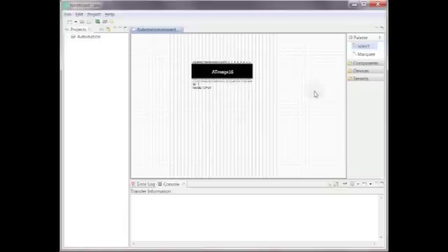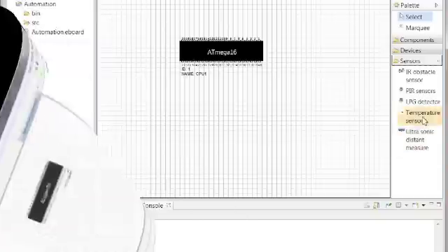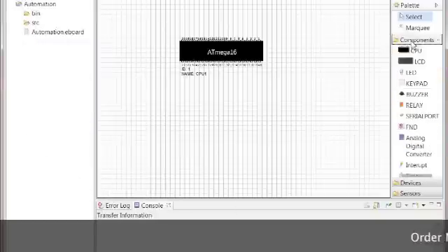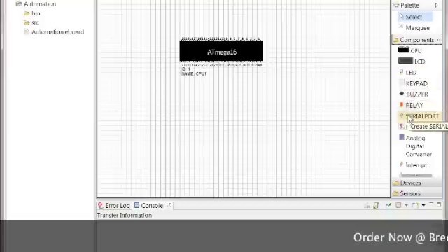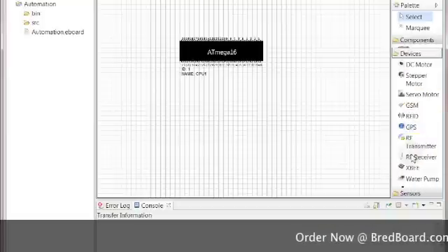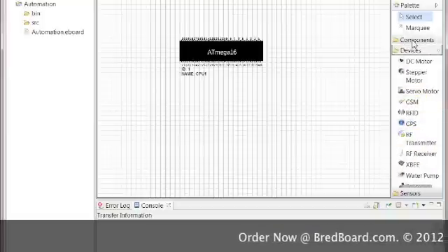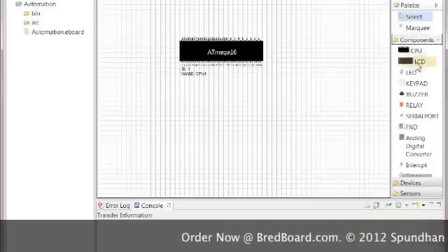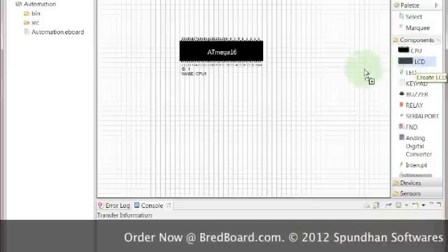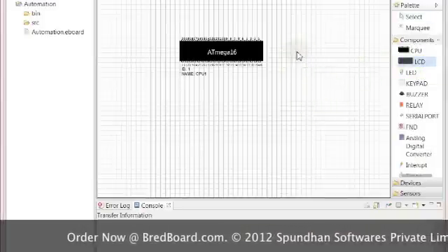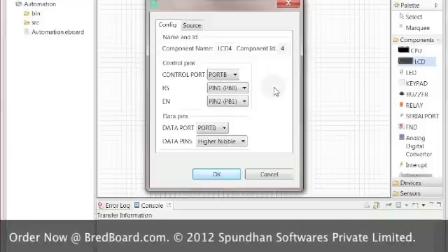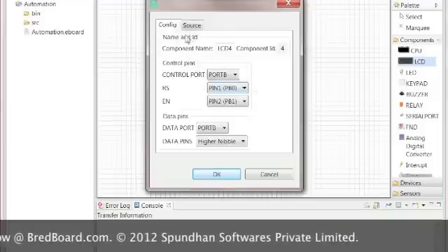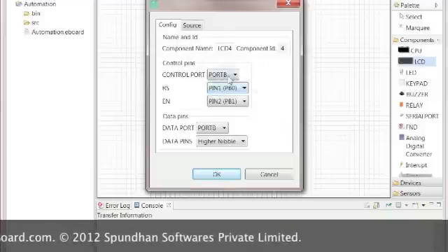This project, by default, contains a microcontroller. For this project we will need a simple LCD display, a relay and a GSM modem. Let's go to the Components section in the palette and look for an LCD. Just drag and drop it onto the model editor somewhere nice. And up pops a small window, suggesting you to connect the LCD on the board.